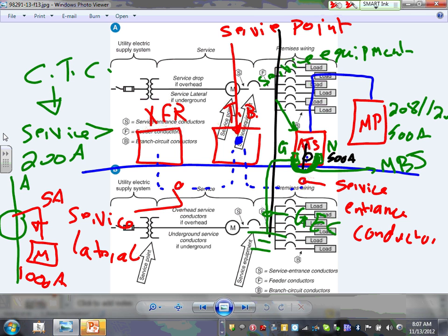What if we were pulling half of this? If, instead of 1,000 amp, we were pulling 500 amps, what do you think the 5 goes down to? Thank you, 2.5. So 5 is the max. That's why you have a CT cabinet. You have a CT, current transformer, that takes 1,000 to 5, 2,000 to 5, 4,000 to 5, 2,500 to 5. So the secondary is always what?